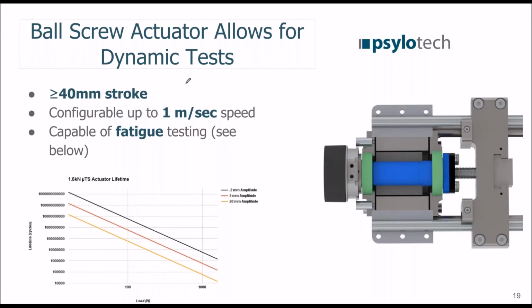So this is one of the key benefits of the load frame that didn't really come up in this experiment, but the load frame is based on a direct drive motor actuated ball screw. So this is the motor, a cross-section view. These are the magnets, or sorry, the windings. The magnets are here directly onto a ball nut. So most other load frames use, first of all, lead screws, which are a lot less efficient and have more play. But we use a ball screw, so it gives us a lot of speed and efficiency for high load, and gets this whole actuator very compactly into this space.